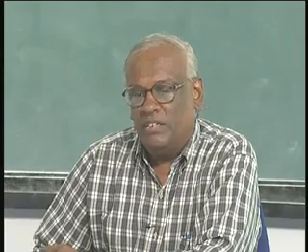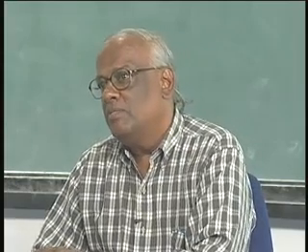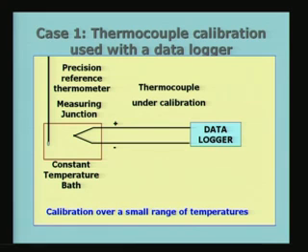So, in the present lecture, what I will try to do is to look at a few cases and see how we can go about making the measurements and also choosing the right kind of instrument for the purpose of making the measurements. The first example I am going to take is with respect to calibration of a thermocouple, and I am going to discuss how it can be done when a data logger is available to us.